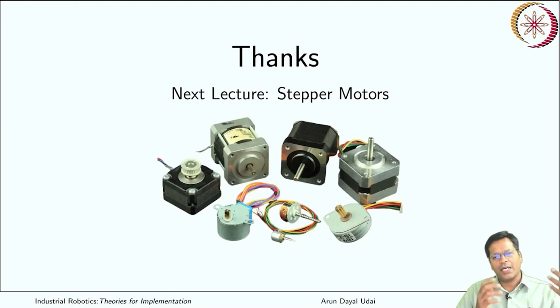You can have various other interfaces too, not just the Beckhoff TwinCAT based system, which is really very expensive. I would suggest you start with a Modbus based system, a Modbus IO card and motor driver card if possible. Otherwise you can have a standard IO card, run a standard H-bridge, and make your motor run. So that's all.